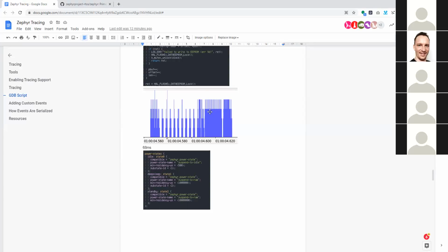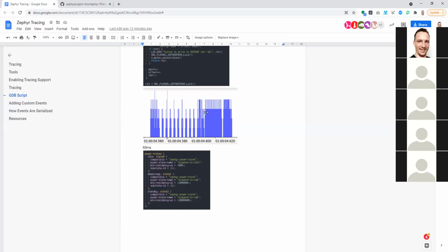One of the interesting things that you can see if you look at this trace is that the application never actually enters into any kind of idle state. It runs an interrupt, and then the interrupt exits, and then the interrupt is called again. So it basically goes round and round. So using interrupt-driven mode doesn't actually improve the performance of the application.